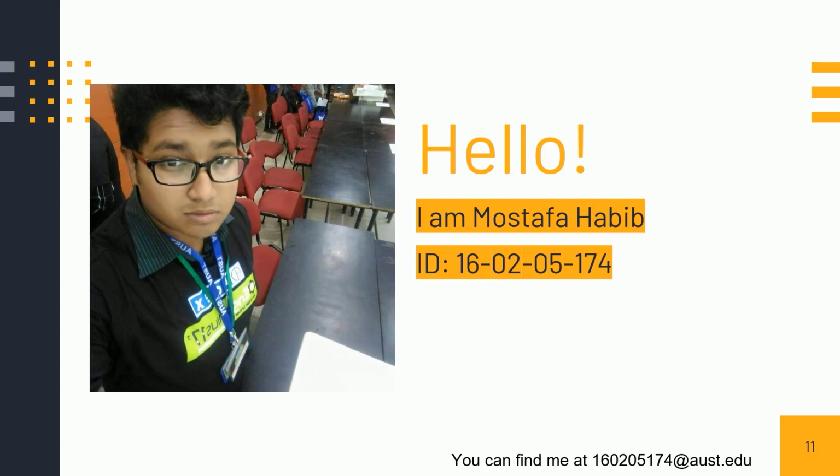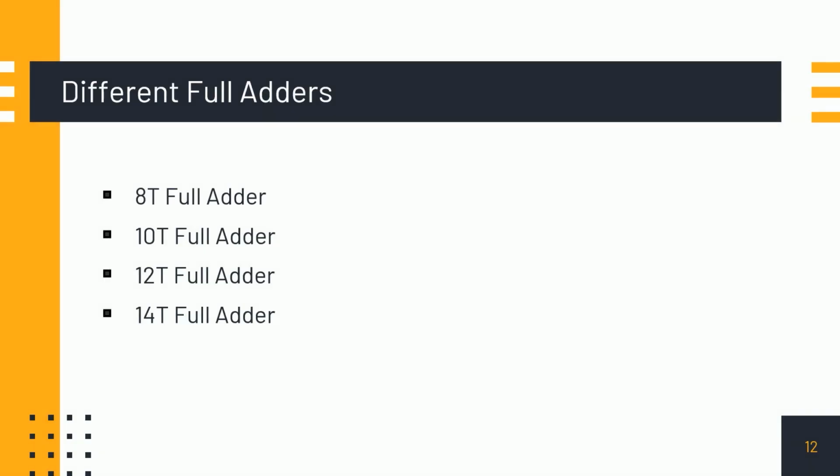I am Mustafa Habib. Now I am going to introduce the different types of full adders that we worked on. Normally, different architectures are used to design full adder circuits. The fewer transistors we can use, the more efficient it will be. Moreover, fewer transistors reduce power consumption. The development of the 14T full adder led to better results for delay as well as power consumption.